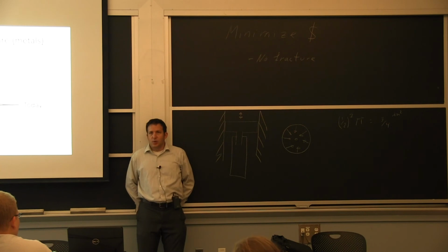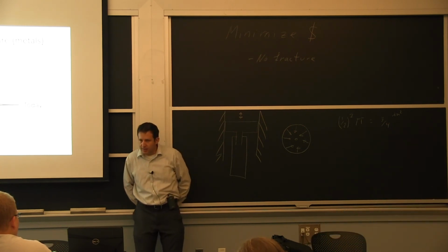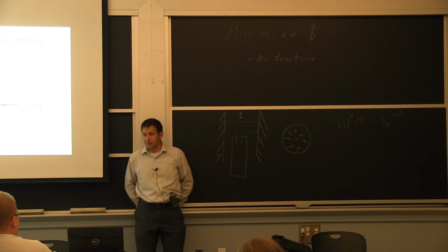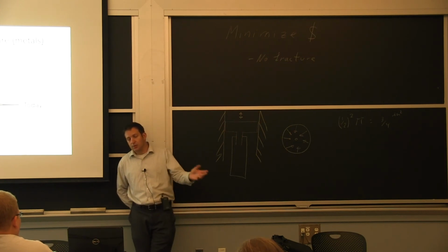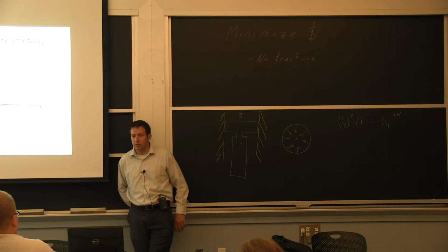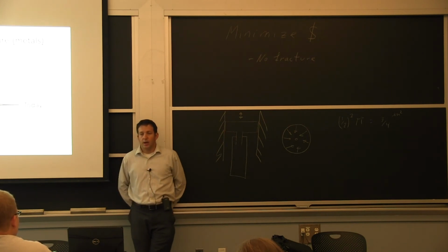So it's one of the basic rules to at least throw the hypothesis, well, maybe this didn't fail all at once. Maybe this is not an overload fracture. So we're going to cover in more detail what I call the slow cracking or the pre-cracking. It can be creep, fatigue, environmental cracking, something that happens slowly, reaches the length, and then you have the overload. That's tomorrow.